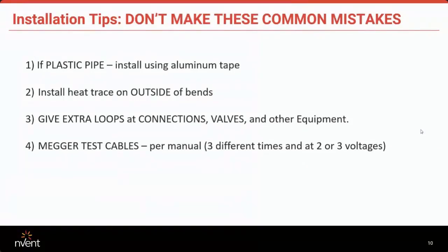These are very important. If you ever have to come back on a different contractor who's maybe come back and maybe they installed the insulation with a screw, a fastener, and accidentally screwed into a cable, you now have those results written down, and you have something to back you and go back on and say, no, this tested fine. Here's where the problem happened.